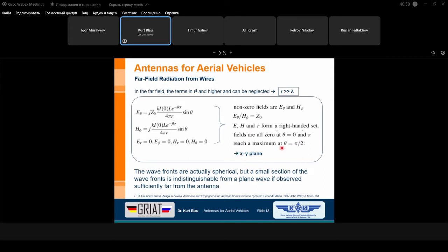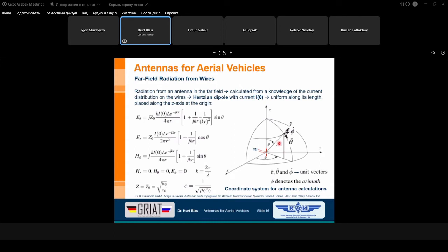Let's switch back. You can see here, this is our dipole, this is the direction, and if you go with our observation point, with a sensor or a measurement antenna, to this point in the zenith, then we will see we have no field. We have a very deep zero, no field in this Z direction, neither an E field nor a magnetic part of the field.